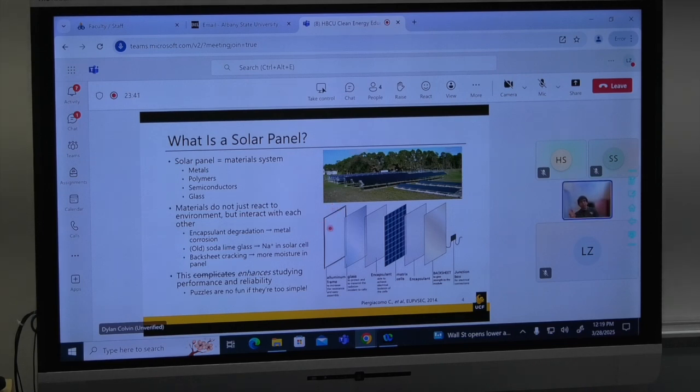So we're used to seeing glass on the front, then you have the cells and then polymer backsheet, but the industry is largely moving towards replacing that backsheet with another sheet of glass. And that in large parts to help insulate those cells more from the environment, but also to help with its mechanical resilience to impacts like hail or heavy weight like snow or wind loads.